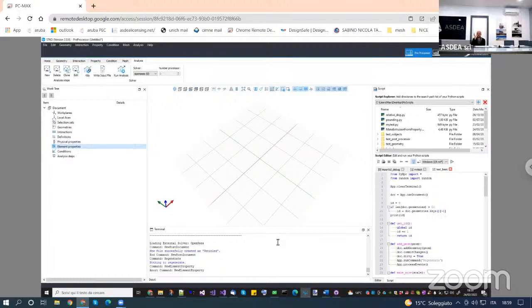So just to have an idea, you can take, for example, the axial stiffness of your beam. So you do EA over L. This is a typical stiffness of your model. Take that one, which is, for example, 1000, that is 10 to the power of 3. My contact stiffness can be 3 orders of magnitude more than that. But do not make it too much larger, otherwise your matrix will be singular.